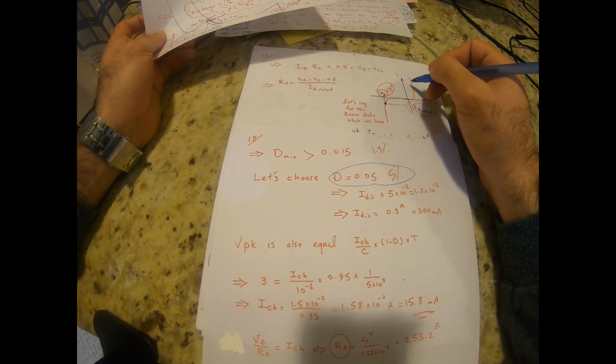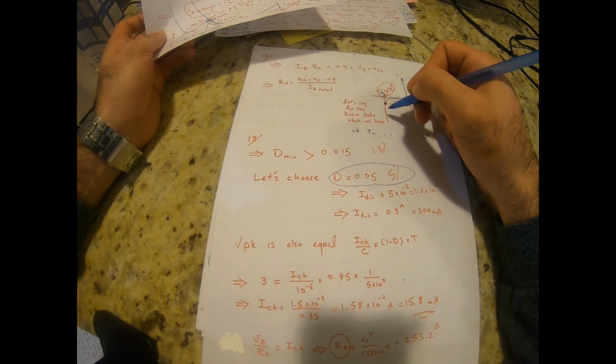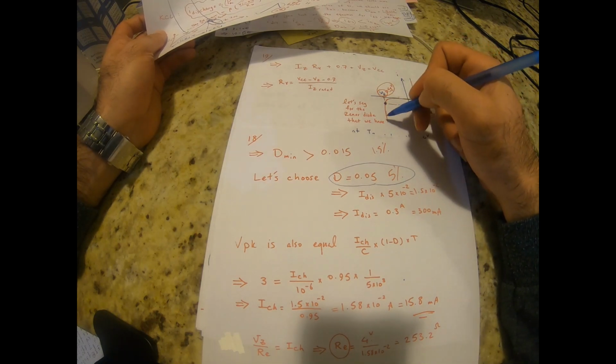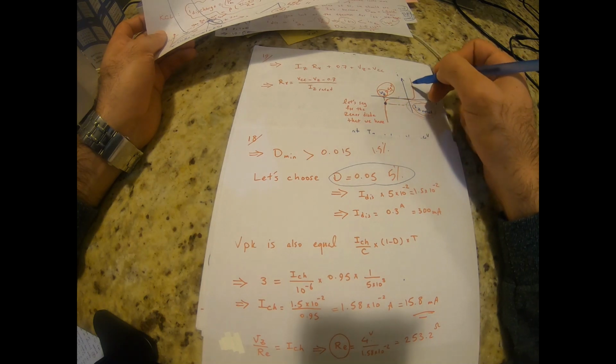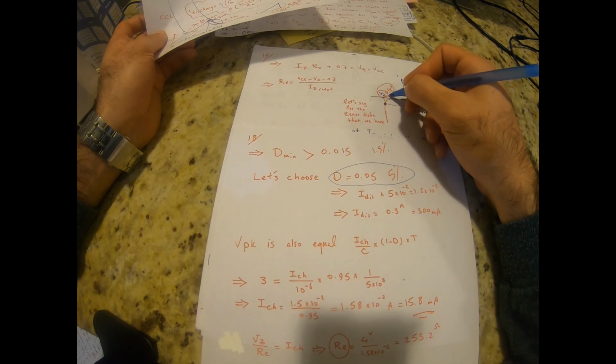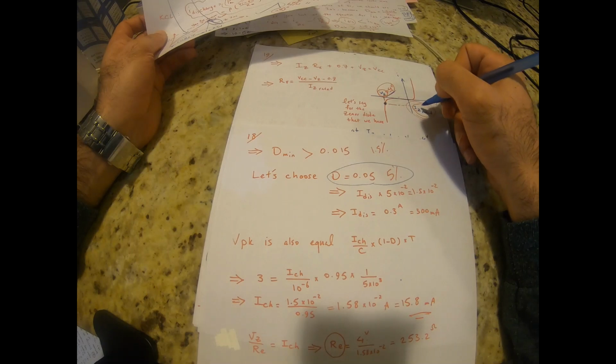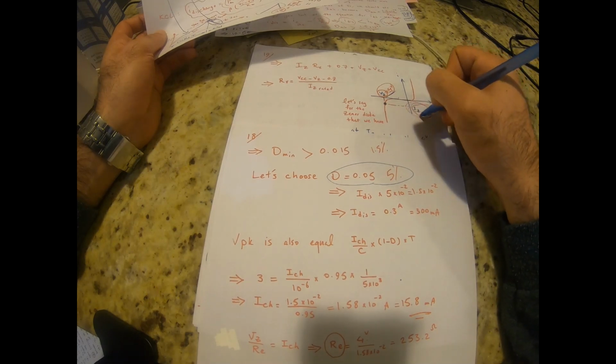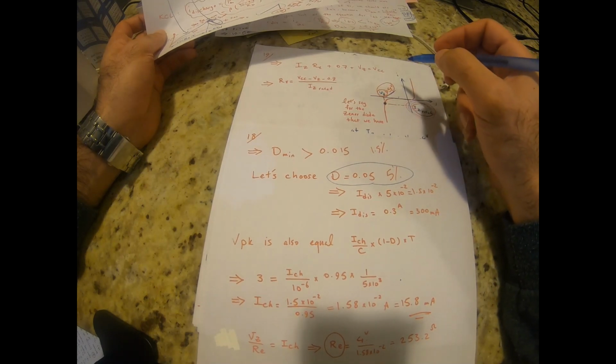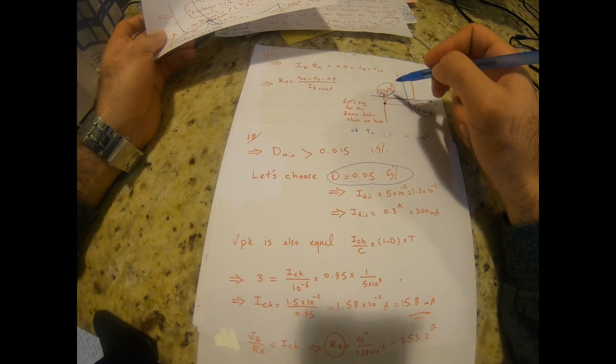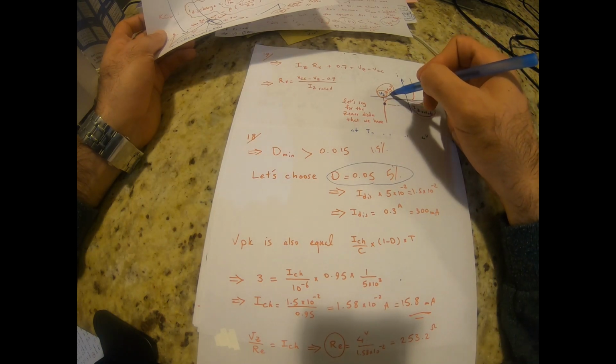Any Zener diode or any equipment should come with a specific data sheet, right? So you can find out based on that data sheet what's the rated current of the Zener diode, at what current we would end up with 4 volt, right?